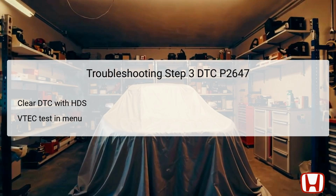This test will assess the functionality of the VTEC system components, including the rocker arm oil pressure switch. If the DTC P2647 is indicated after proceeding with the VTEC test, it suggests a persistent issue that requires further investigation. On the other hand, if other pending or confirmed DTCs are present, addressing those will be critical before retesting for P2647 to ensure all potential faults are accounted for.